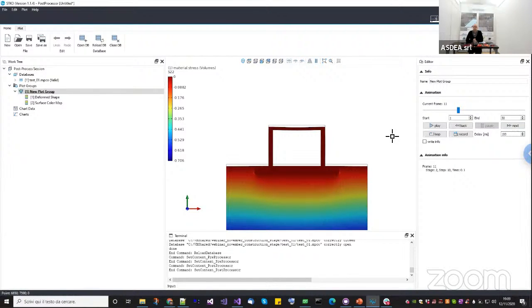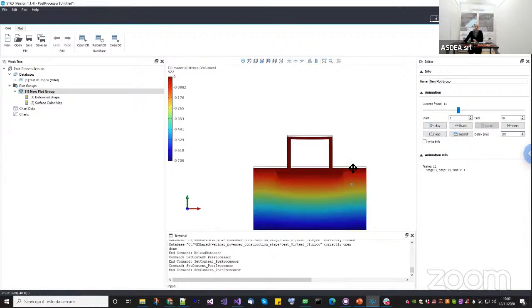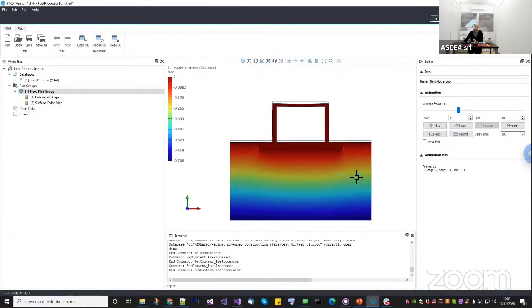But if I was doing a dynamic analysis, this was actually a great problem because instantaneously the displacement will go from a value to another. And this one will actually create huge acceleration at that point, depending on the magnitude of the initial displacement. But since the initial displacement will be reset to 0 instantaneously, you will see probably some spurious oscillation in the accelerations.